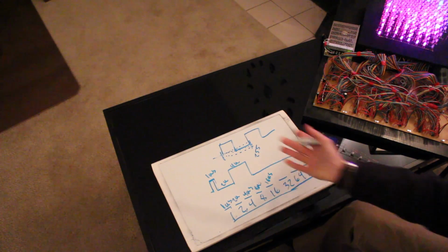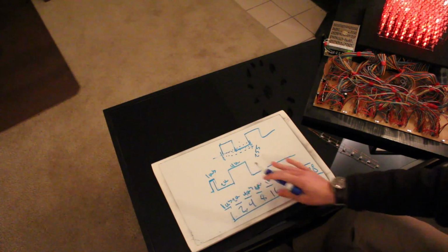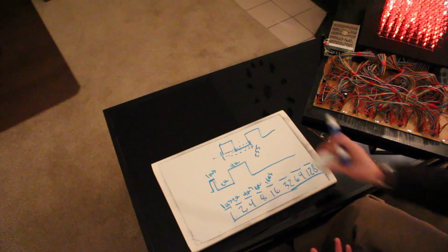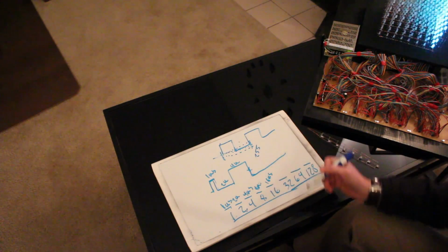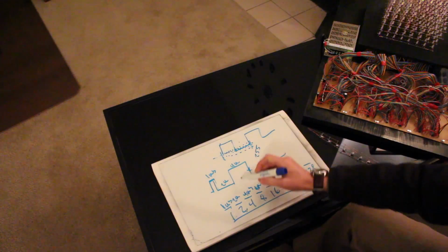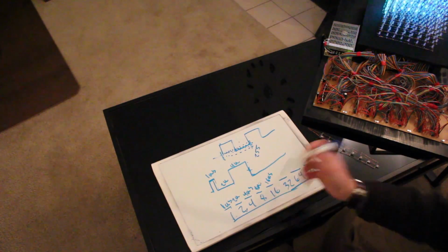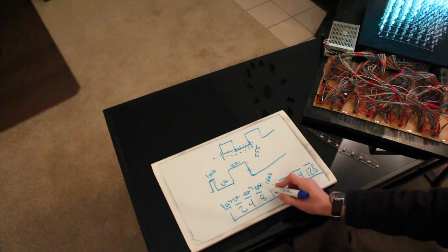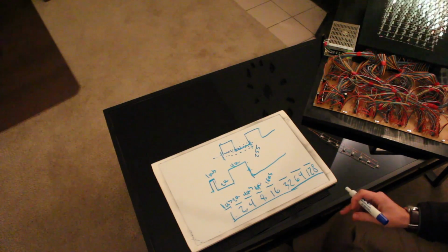Then you repeat that just like you did here, but notice how we sort of have a goofy waveform, and that's how bit angle modulation works. The reason this is so nice is that in this case I showed you have to keep checking it. In this case, if you knew it was 4 microseconds, just let it hang out there. Don't update it until it hits 8 microseconds. So if you have your free running timer, it kind of makes things simple.